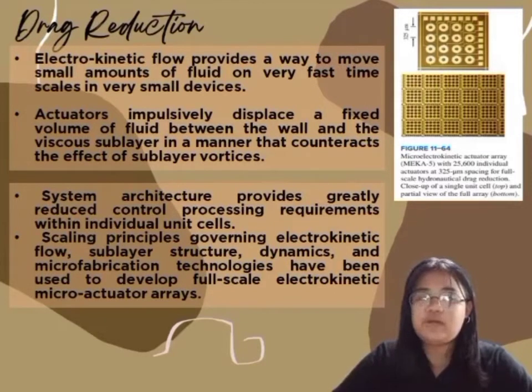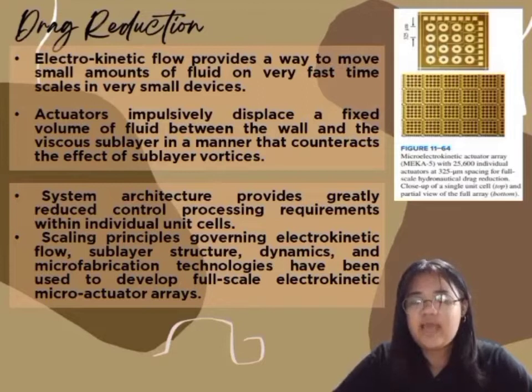Also, scaling principles governing electrokinetic flow, sublayer structure, dynamics, and microfabrication technologies have been used to develop full-scale electrokinetic microactuator arrays that can meet many of the requirements for active sublayer control of the turbulent boundary layer under real vehicle conditions, that may in the future allow engineers to achieve dramatic reductions in the drag acting on practical aeronautical and hydronautical vehicles.